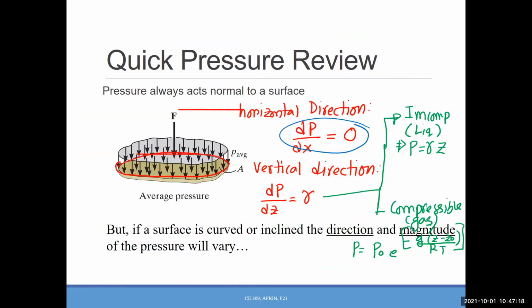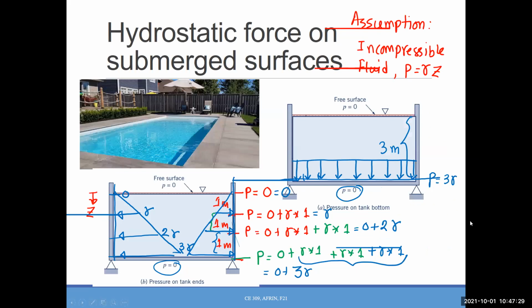What is the pressure variation here? You see, you have a pressure here, temperature here, ideal gas law, and the distance and everything. So one good point to be noted will be, just write down that for compressible gas or compressible fluid, you can have different type of pressure profile because temperature will play a role there.